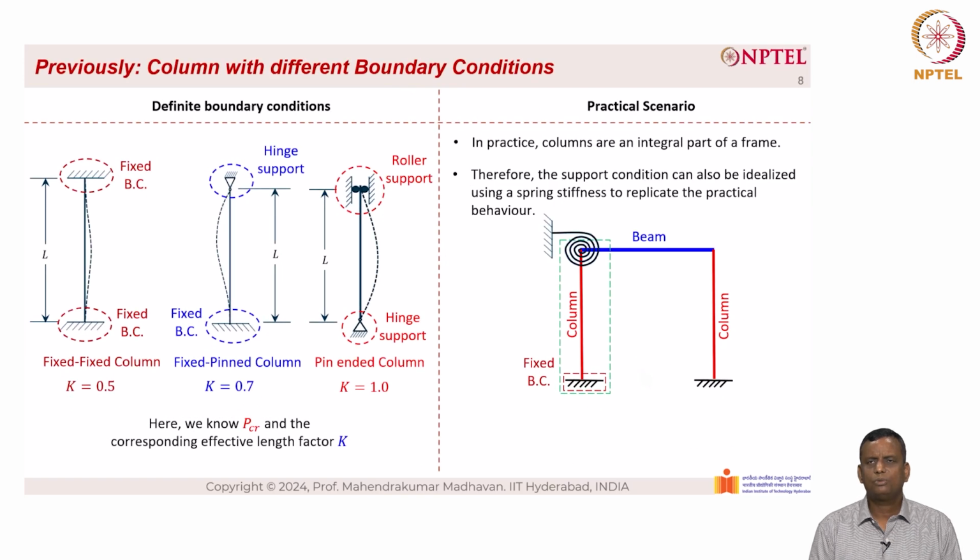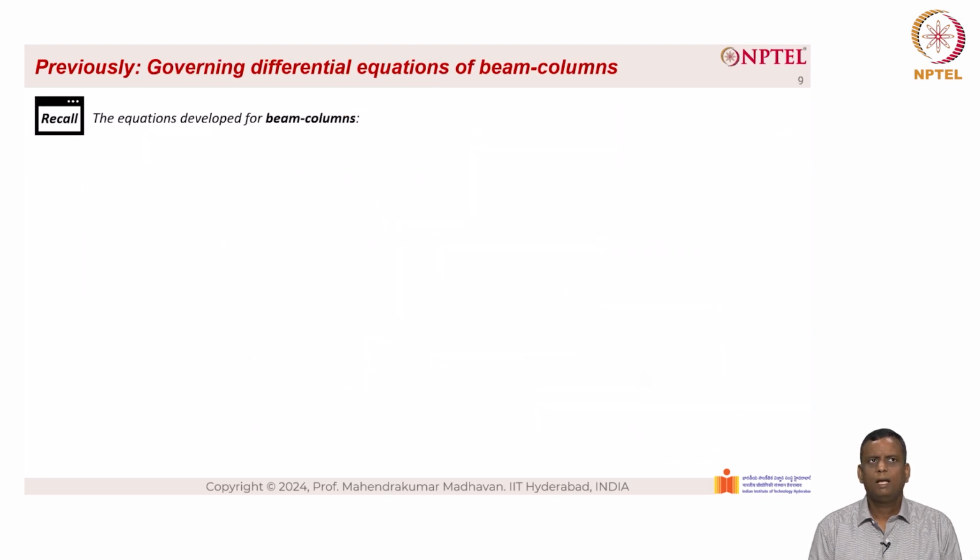Now, in order to understand this more carefully, the support condition can also be idealized using a spring stiffness to replicate the practical behavior. To analyze such columns, a more generic method of solving the differential equations used is known as the matrix method. Now, previously, we understood the governing differential equations of the beam columns.